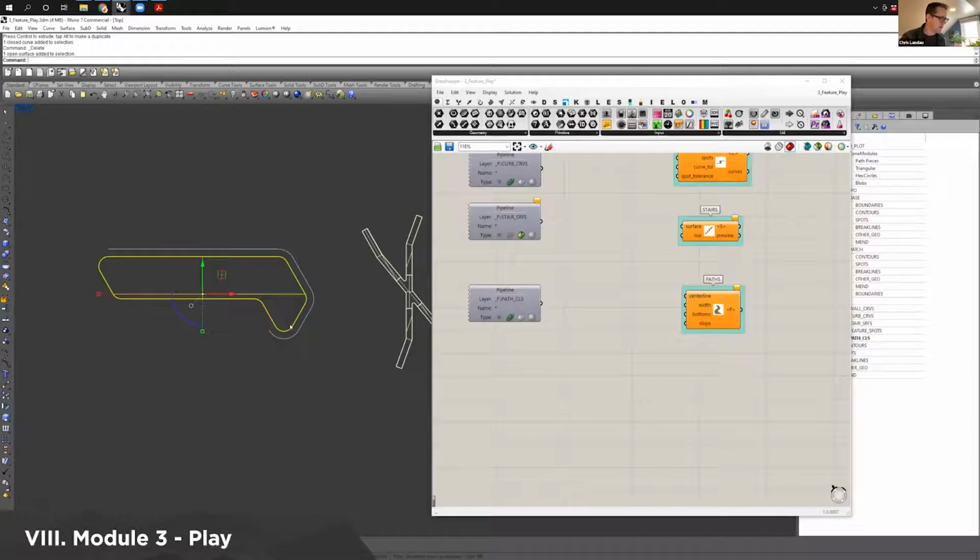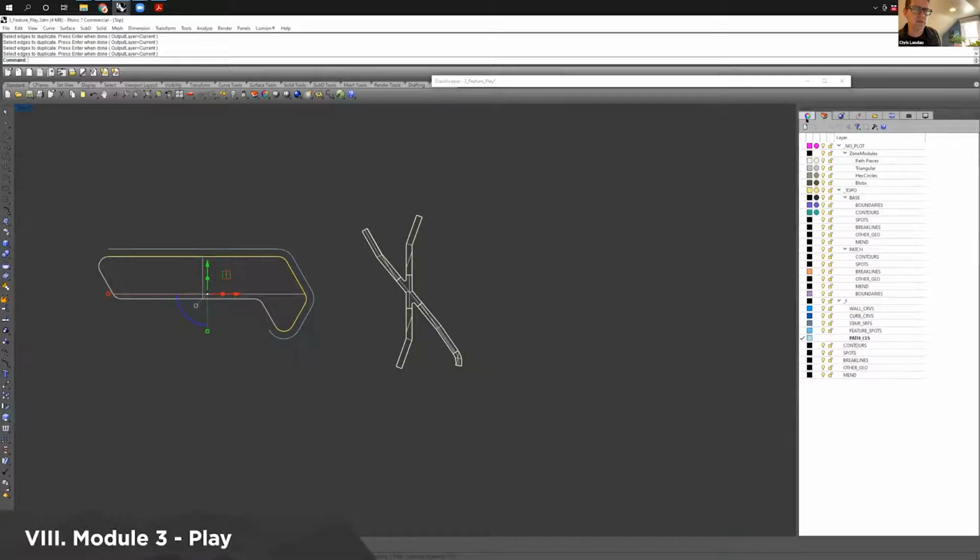I made that curve, so I'm going to do it again. Dupe. Well, you can also do dupe edge. So dupe E, and it autocompletes, and then you hit return. You select the edges you want to duplicate, and then say return. And then because it's a bunch of separate edges, I think, I can't tell. Let me see over here.